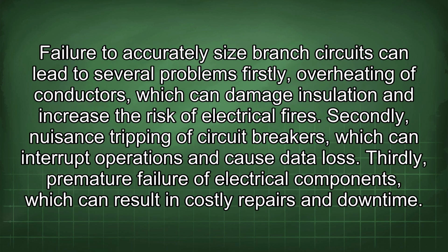Failure to accurately size branch circuits can lead to several problems. Firstly, overheating of conductors, which can damage insulation and increase the risk of electrical fires. Secondly, nuisance tripping of circuit breakers, which can interrupt operations and cause data loss. Thirdly, premature failure of electrical components, which can result in costly repairs and downtime.